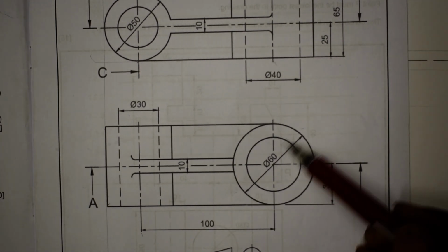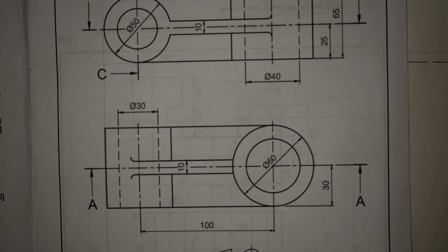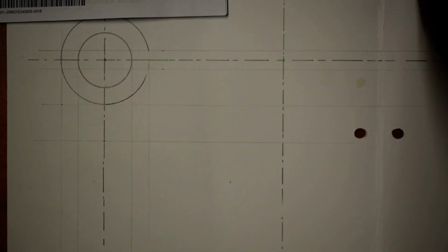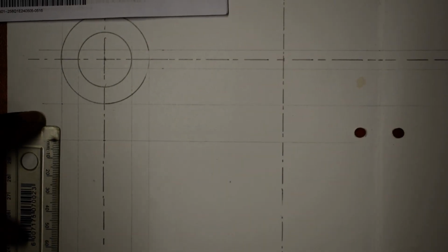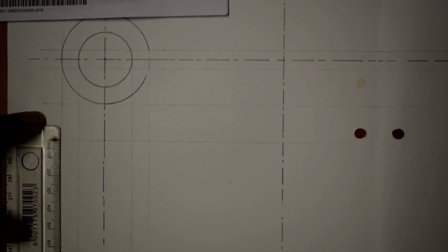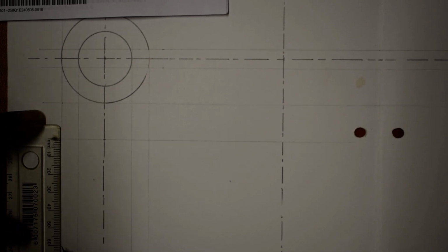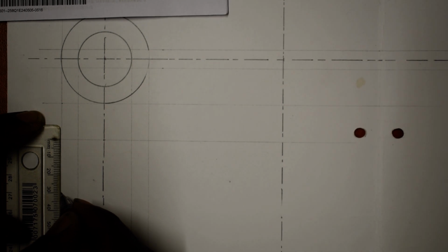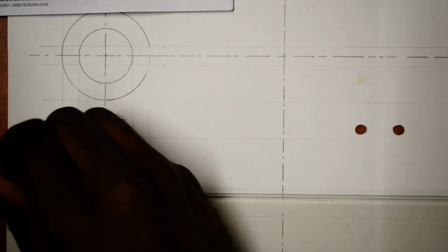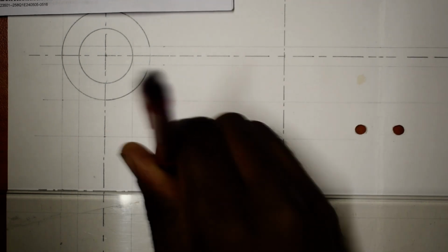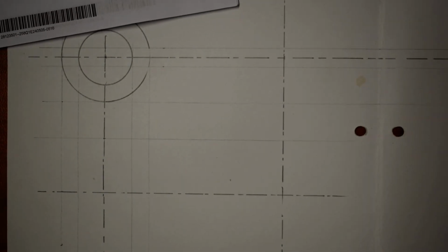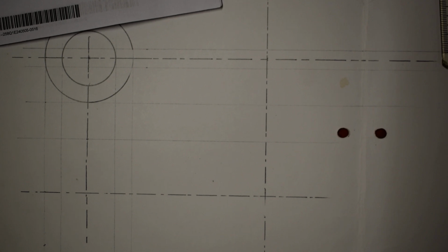So we are actually told there by our right hand side of our top view, this side. Okay, so now what I can do, I have to get the horizontal center line. Simply place it here, then I mark at 60. You see, I mark it 60. Then what is the half of 60? Where is my 60? Right here. The half of 60 is 30. So at 30 I can draw the horizontal center line, like that. So if I'm to such an extent, then I can draw diameter 40.